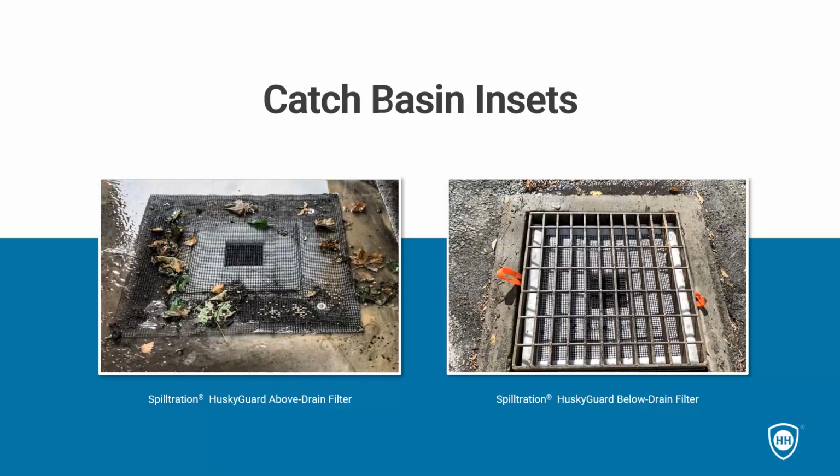Great because they can capture silt and sediment, they can capture trash, they can capture oil sheens. There are also things available with catch basin inserts that can help you collect heavy metals or organics or other pollutants that may be of a concern for you, possibly something that you're not currently meeting within your permit. Catch basin inserts are a way to possibly capture that before it becomes a problem for you and before it becomes something that could cause you to violate your permit.